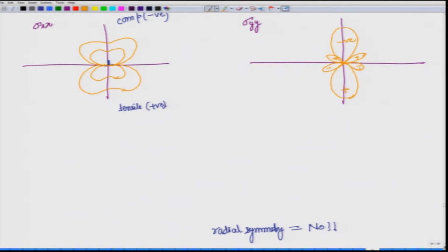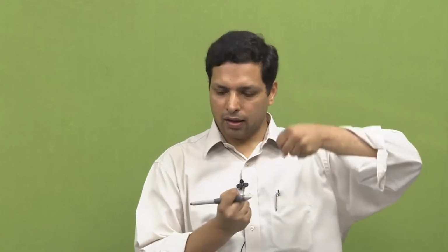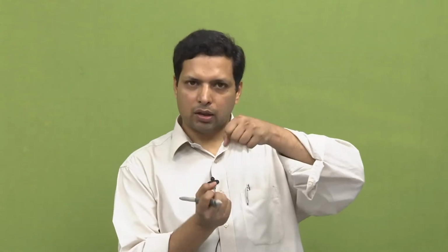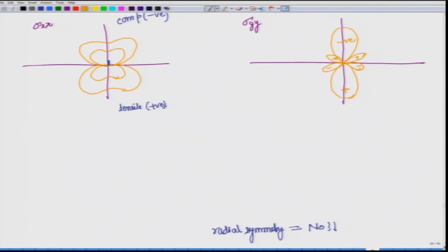So, we are talking about the normal y direction. Here you have the tensile even in the y direction and in these two small lobes, and on the positive y side we have negative, meaning compressive, the atoms are being pushed together. So, this is the negative, and so is the negative over here, the smaller two lobes, and this is exactly at 45 degrees.